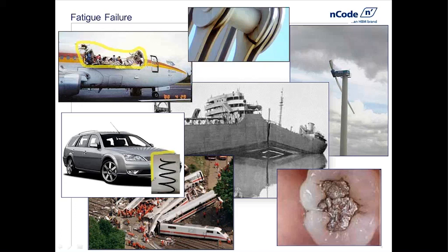This is another fatigue failure. This is a spring in a car. This spring got into a bit of a disagreement with itself and decided to split in half. A spring is a great example of something that sees a fatigue load because by its very design, it's meant to be cycled through stresses or through large deformations. Each cycle can lead to an accumulation of what we call fatigue damage and can lead to progressive failure.